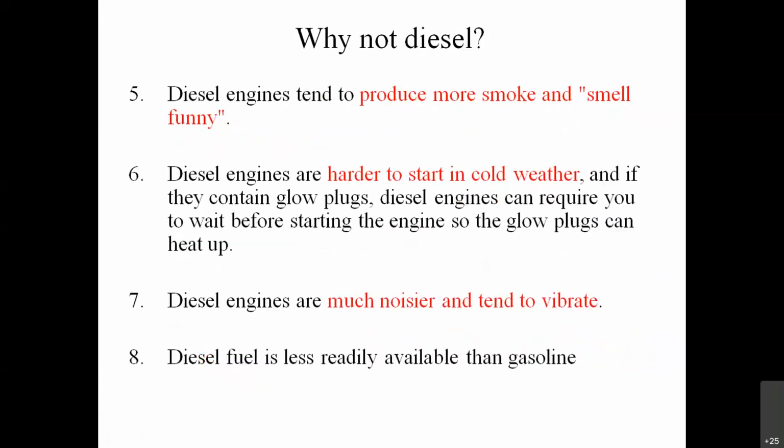This tends to make diesel cars slower in acceleration as compared to SI or petrol engines. Another disadvantage is that they produce more smoke than petrol engines. One more drawback is that they are harder to start in cold weather, so diesel engines need to be in continuous use.